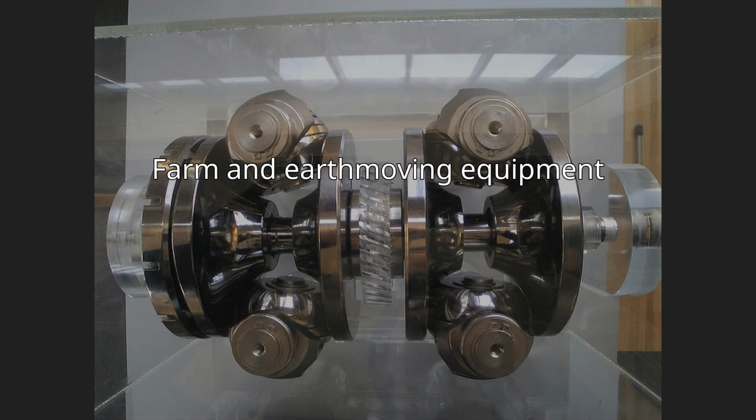Farm and earth-moving equipment. Combine harvesters used variable belt drives as early as the 1950s. Many small tractors and self-propelled mowers for home and garden use simple rubber belt CVT. Hydrostatic CVT are more common on the larger units. Hydrostatic CVT are used in small to medium-sized agricultural and earth-moving equipment. Since the engines in these machines are typically run at constant power output to provide hydraulic power or to power machinery, losses in mechanical efficiency are offset by enhanced operational efficiency.